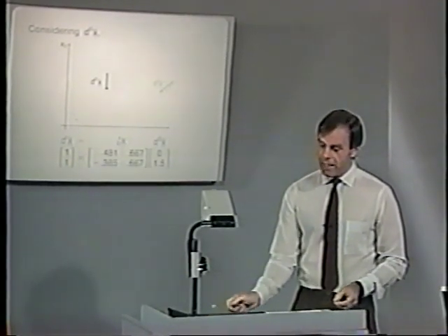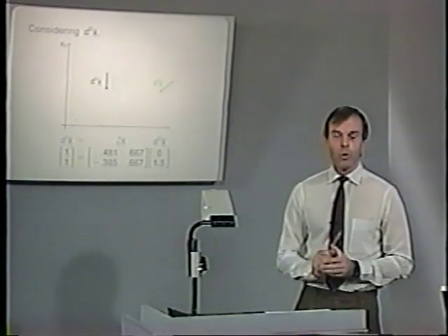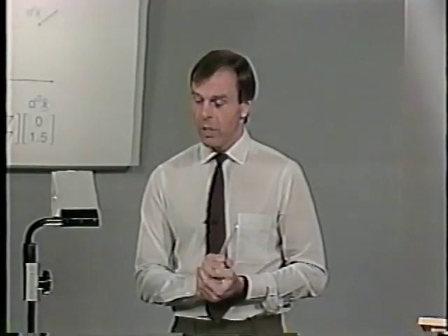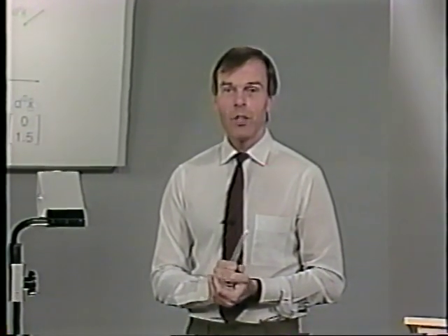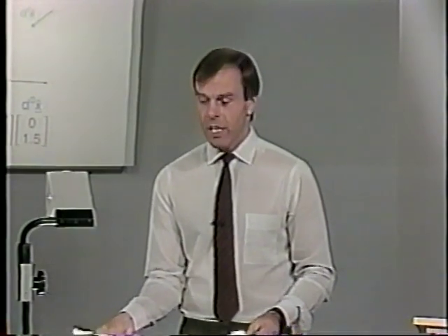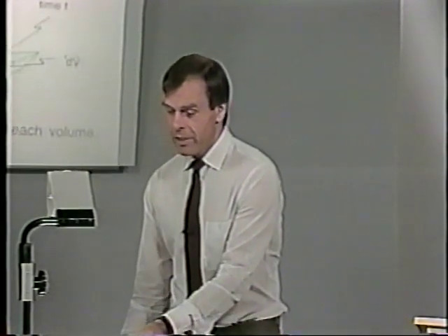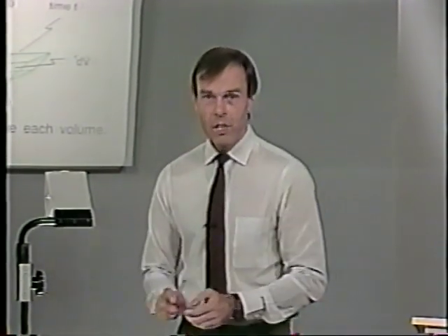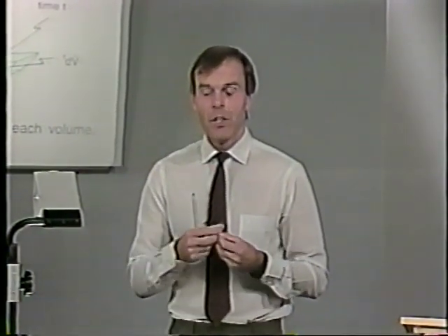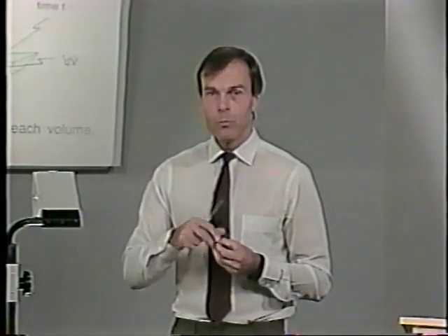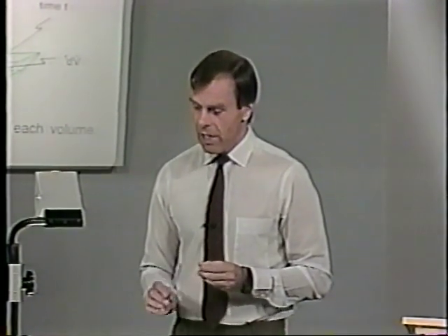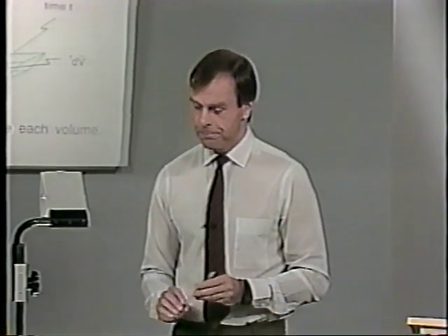The deformation gradient is very useful for various measures, computations that we perform in finite element analysis. And one such computation is to calculate the mass density ratios. In other words, we have to assess how the mass density of the body, as it moves through the space, changes. Let us look at how we do that.